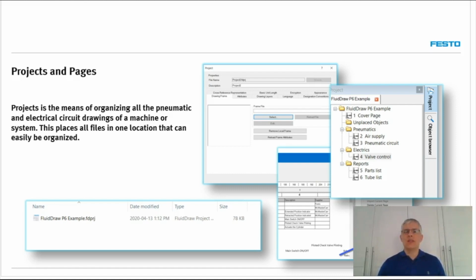This way, you have a systematic way to make sure that all the drawings are going to be named in a certain convention, located in a certain convention, including, if you like, the drawing size. Is it an A4, A0, whatever format you want to standardize on? This can be already pre-done in a template that can be easily stored and saved for future projects.